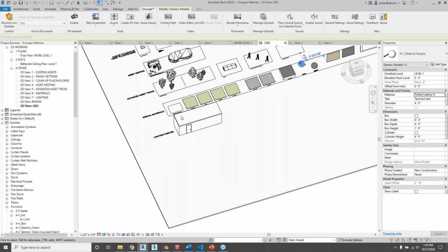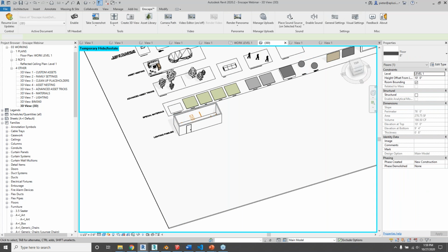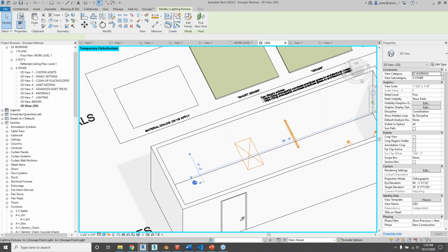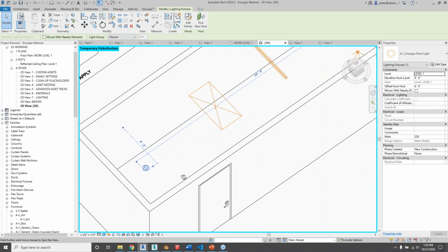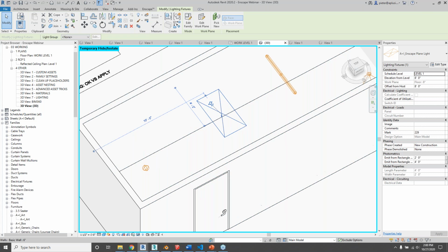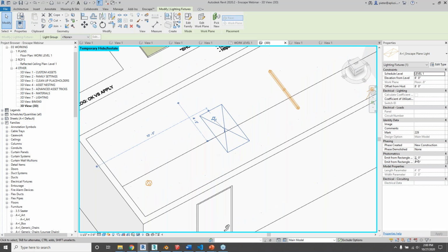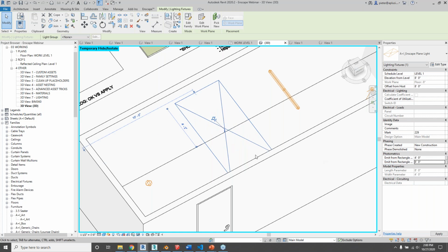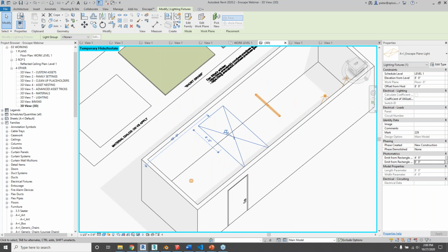And so the trick is how we did this in Revit is, and I take the roof off here, you will see our families. So these families are lighting families, but they only have model lines in them. So they're easy to find and place, but model lines are rendered in Enscape, so they don't show up. And we have a filter that can take them out of our drawings, or you can put them on a work set together with your assets. And we made every parameter that we could instance. So like this plane is instance scalable. So it makes it really easy to play around with lighting.